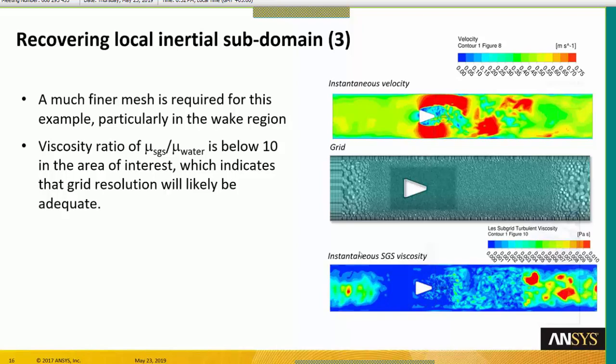That means that we are diffusing very rapidly the kinetic energy content. At this probe, this is a good indicator that here you have a problem. You are dissipating too quickly all the turbulent information you have at this probe.